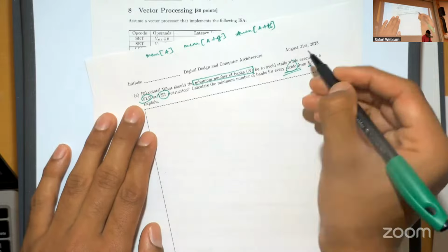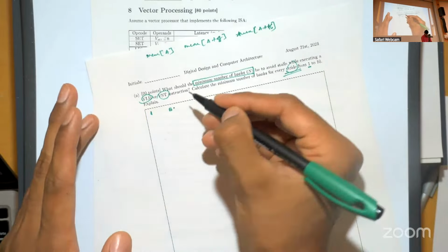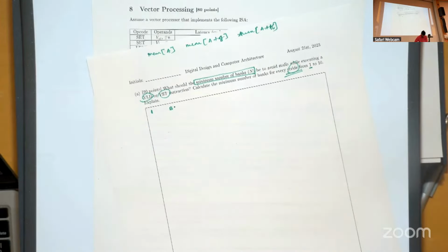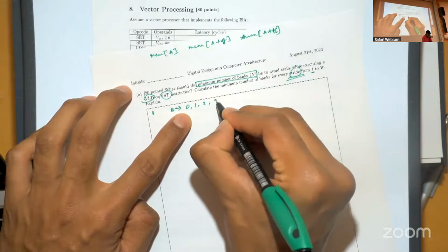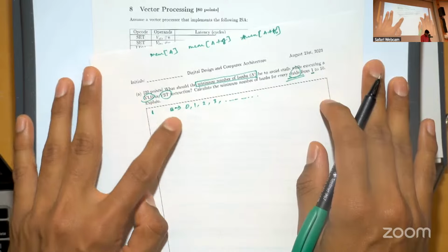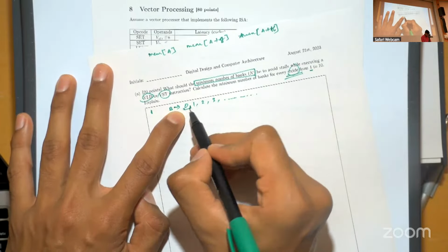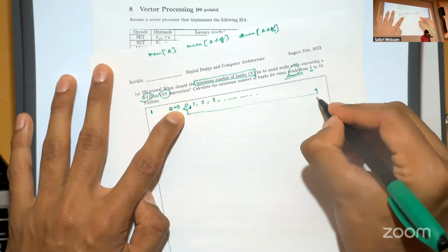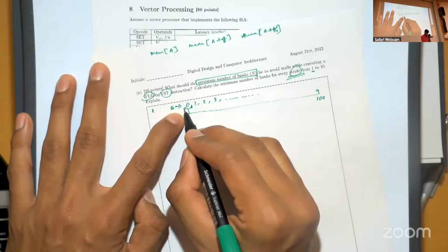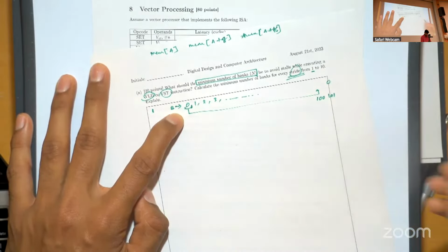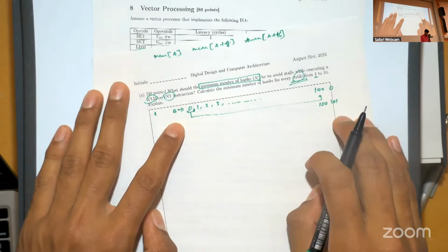And so let's say we have a stride of 1. Then the banks that you would access would be bank... let's start with, how do we index it? Let me follow what they do here. Okay, let's start with 0. So you would access 0, 1, 2, 3, and so on, right? The memory access latency of this is 100 cycles because it's a row miss, which means that the data of this is going to come back at some point in the future, and that is at the timestamp 100. Which means that you can only send another request to the same bank at cycle 101, right? Therefore, if I were to have 100 banks, I could get away without incurring any stalls.